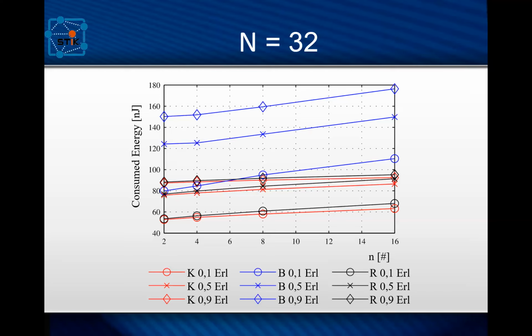The next analyzed algorithm is the pseudo-random algorithm. The selection of the middle section switching element checked for availability for the new connection is determined by a pseudo-random number generator. And the last considered algorithm is the Benes algorithm, very often used in telephone exchanges. The order of checking the middle section switches is determined by the number of connections passing through each switch.